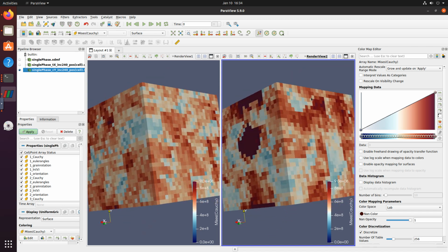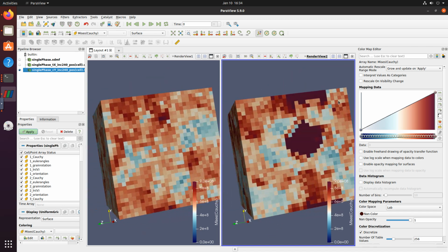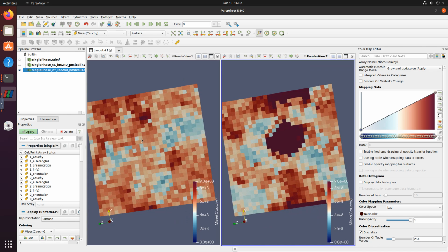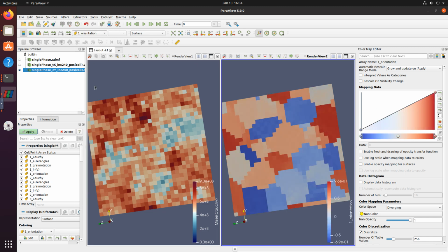This is what we see here, and similarly, for example, it will be quite nice to see. So this area here was relatively relaxed, but now it has significantly higher stress, and now the lower stress is distributed here, which was relatively at higher stress earlier, right? So martensite has taken up a lot of stress in this strain regime, up to 10-11% of this, and we can also do that, for example, for